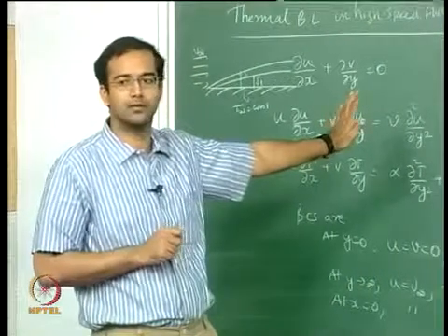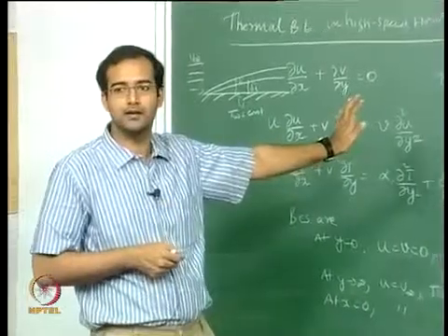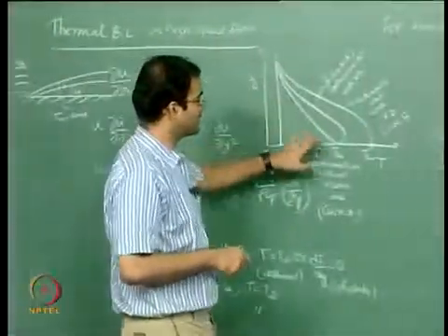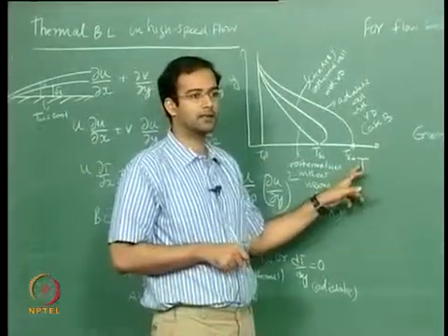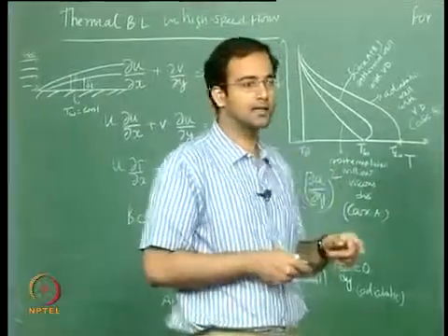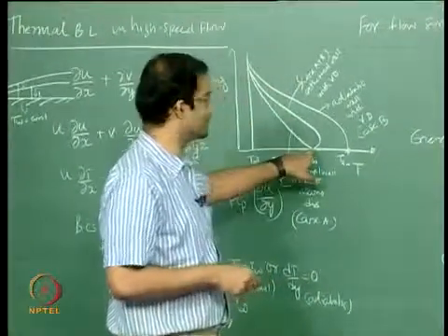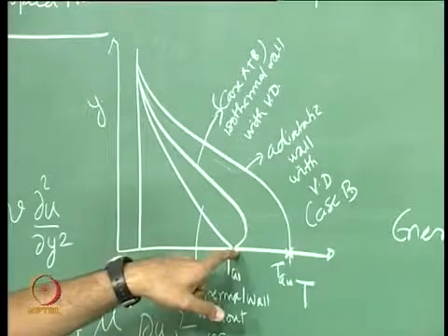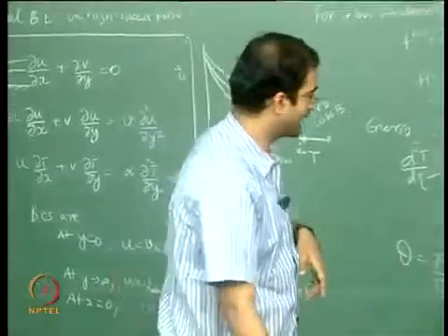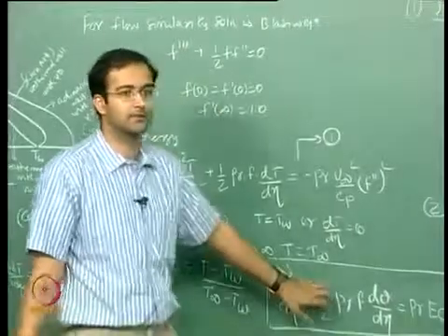So this is why I am doing it this way. Assume that you have two solutions, one for isothermal case, the other for adiabatic case. You can combine them directly. We will see how we are going to combine it, and that will give your generic case, isothermal wall with viscous dissipation. Otherwise you could have directly solved this equation by shooting method.